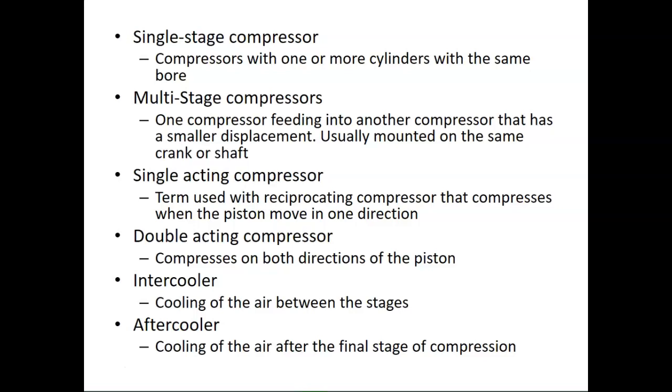So intercoolers and aftercoolers are a marvelous thing to have because these cool the air either between the stages or at the final stage of compression. In other words, after you stick all 50 people in the room for about 10 minutes and they are all getting aggravated, you crank the AC as it comes out. Or you crank the AC as you throw all the people in and everybody's a little bit easier to deal with. Does it make sense?